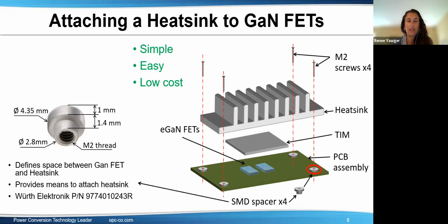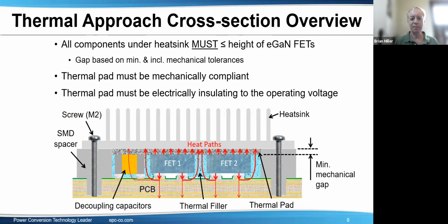A higher number of vias helps in reducing the temperature at the upper layer, but what about when there is a multi-layer board? The lower layer gets affected. How do we take care of that? Yeah, that's true. The other layers do get affected, and that's kind of the point. The idea is to get the heat coming down to these bottom layers. So yeah, you're right. If you have other parts on the bottom side, yes, they will get heated because they'll spread the heat from just the top and the more vias.